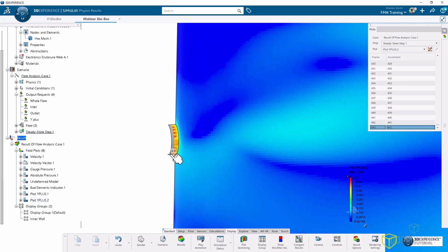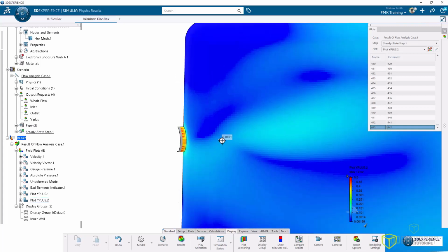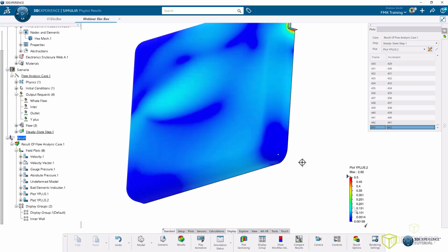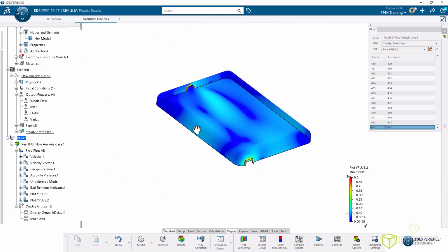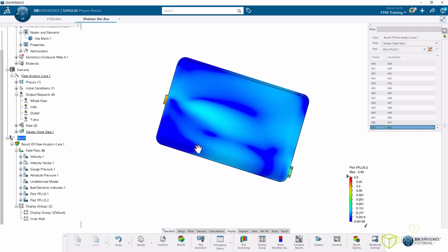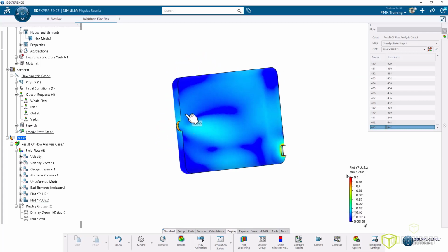And really what I'm looking for is the biggest possible cells relative to the flow characteristics there that won't cause problems with the meshing. So I have big ones here, those are fine. But what I want to find out is where are the ones that are too small. So I can see here, oh, this is dark blue here. This may be still not quite as, excuse me, it's probably not quite as refined as I want.